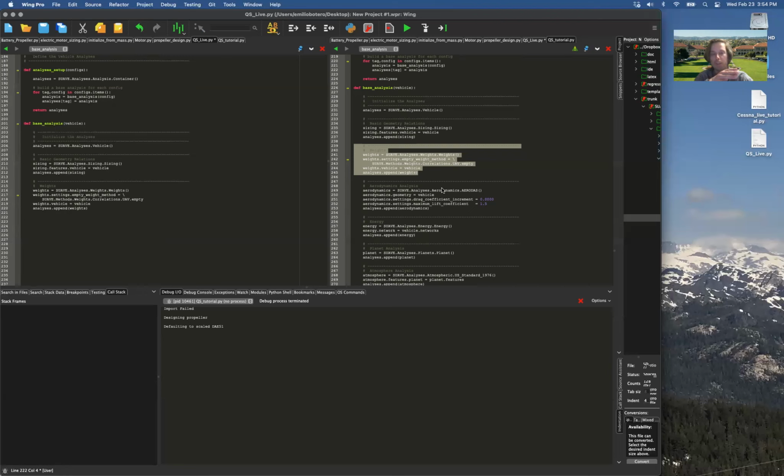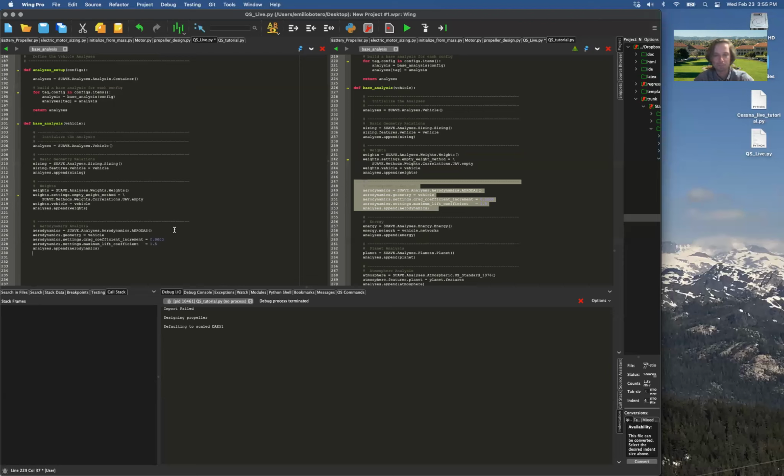We had specified, if you recall, just a symmetric airfoil that is 12% thick. So it's going to assume an NACA 0012, and it will build up the drag polars to make it actually transition through. So this is pretty simple, just specifying that and adding it in.